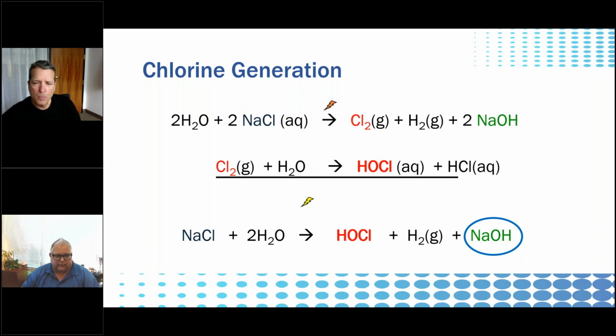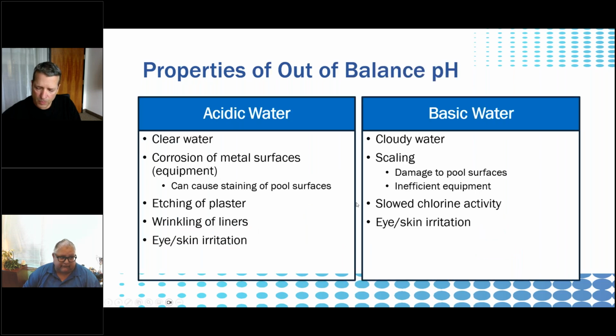So part of saltwater pool maintenance is constantly bringing that pH back down to where it's supposed to be to ensure that swimmers are comfortable and to ensure that ultimately the chlorine that you're making and relying on to do the work is able to work effectively and efficiently.